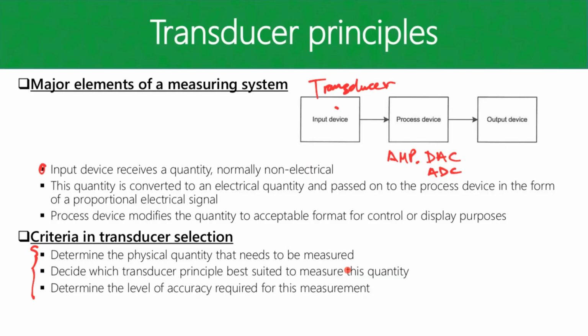Whereby some transducers will only give you an output if there's a change in distance. So if the distance doesn't change, it's not going to produce any output. Right. So you need to decide what you want to do there. And then also on that second point is what is the kind of displacement that you have? So is it very big displacements or is it very small? For instance, you're not going to use an ultrasonic sensor for very tiny displacements.